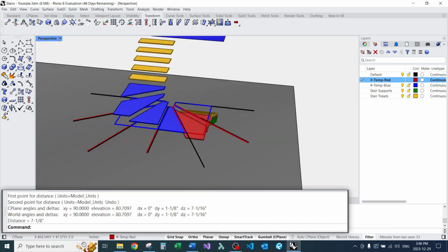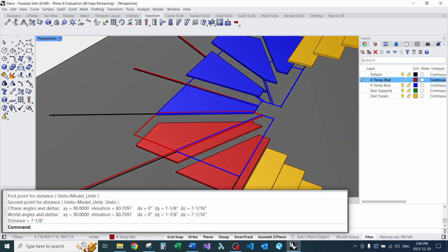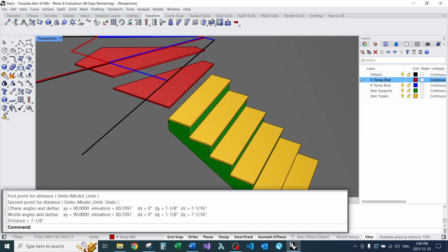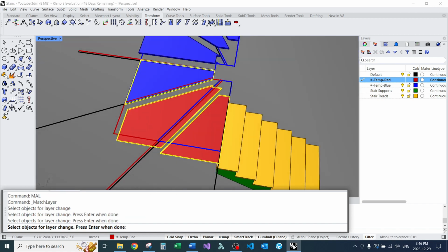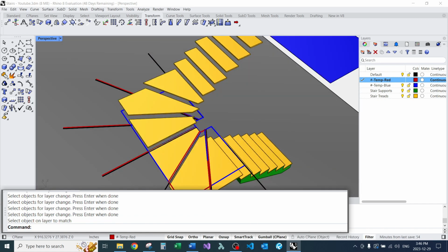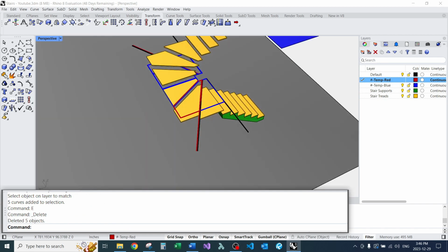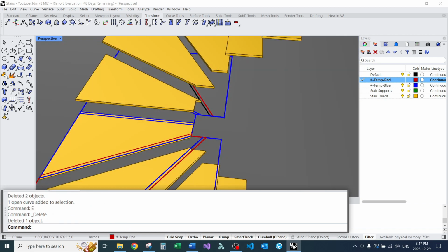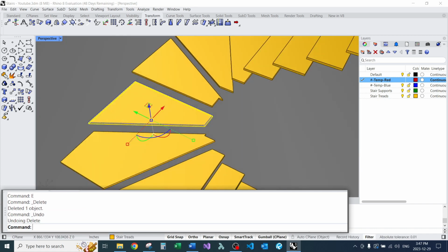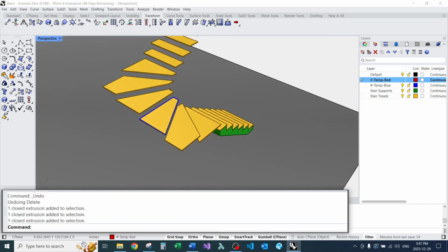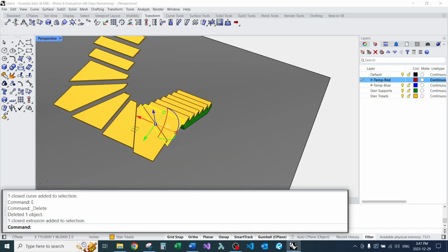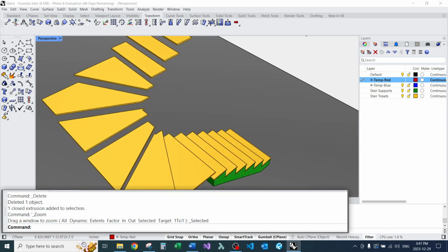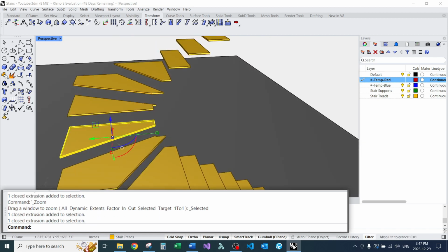So now I'm making a good business case for a Grasshopper script, but to be honest, the problem with automating winder stairs is that if things deviate outside what the script can do, you'll have to manually model them anyways. But I think there are things available. When I showed you Visual Arc earlier, you could use Visual Arc to get your treads. And if you don't like the mass modeling beneath the stairs, you can just explode the stairs and just keep the treads, right?